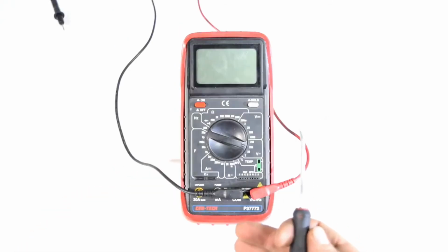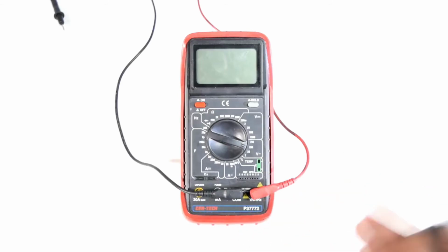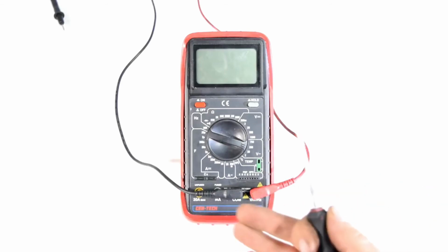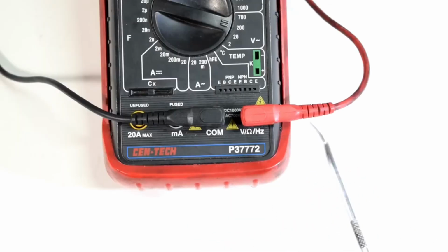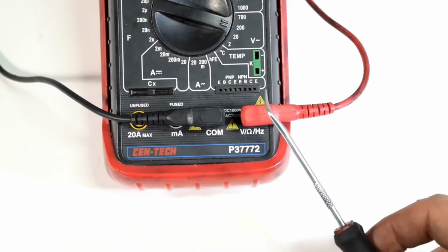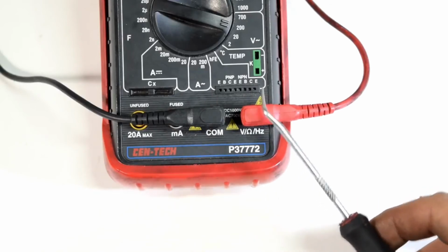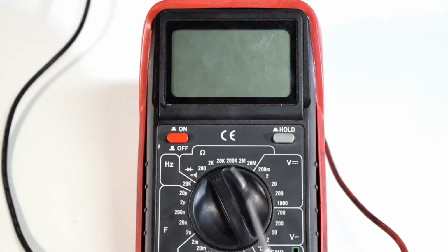Now, different components of an electric circuit are supposed to have a certain amount of resistance so that the whole system works properly, and that's where knowing how to exactly measure resistance is very crucial. Now, when measuring for resistance, your black test lead stays in the same place, and on this multimeter, the red test lead also stays in the same place because this horseshoe looking thing is a sign for resistance. And we put our dial here where we get the scale for resistance.